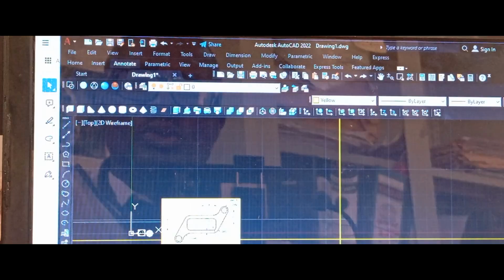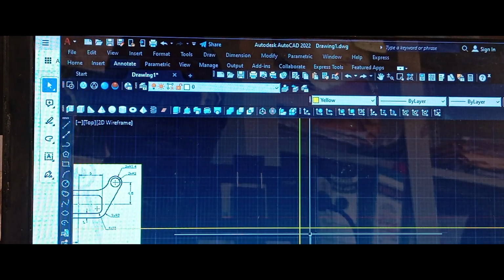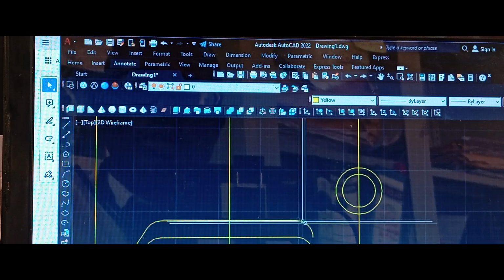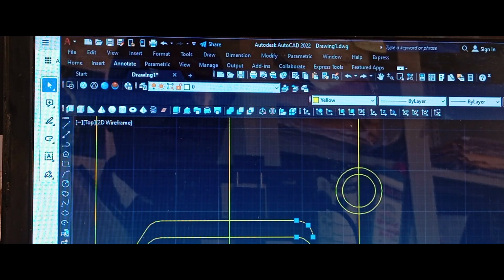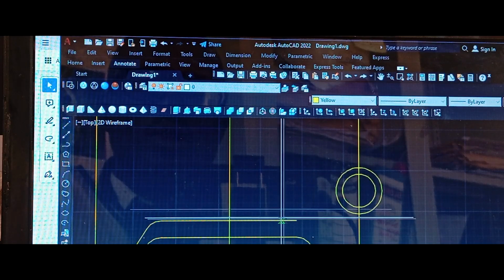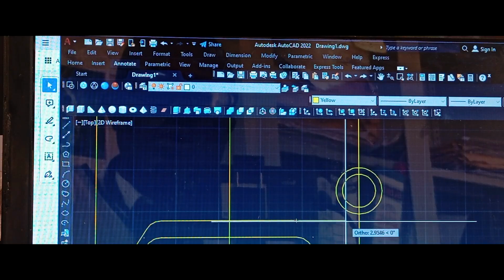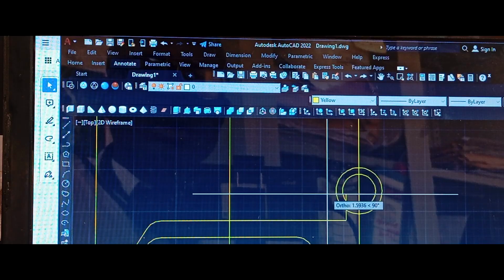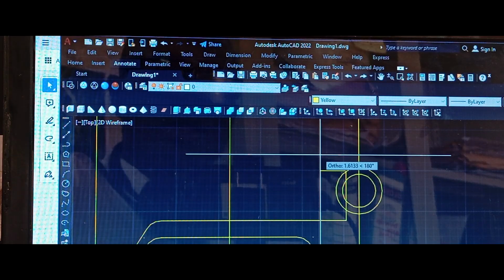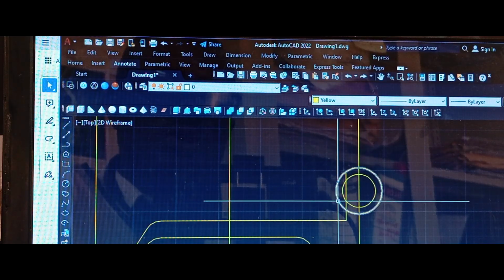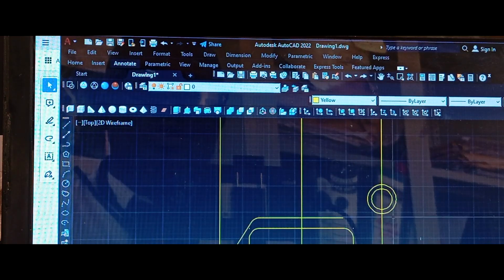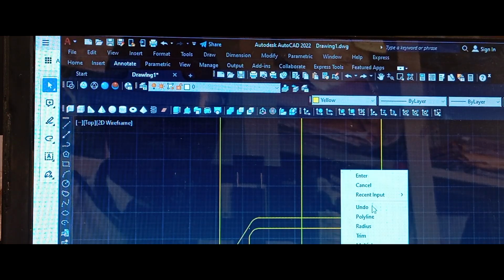Yeah. So let's see what happens if I say from here I do 3. This 3 is a bit long. I'll go up by 3. Is that going to give me what I was looking for? No. No. What I'm just going to do is fillet and say 3.